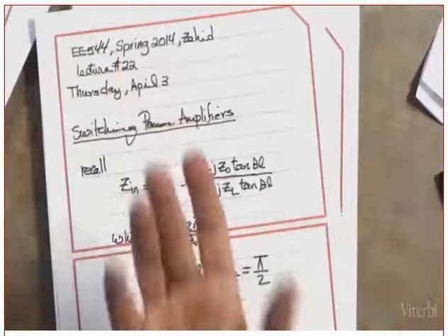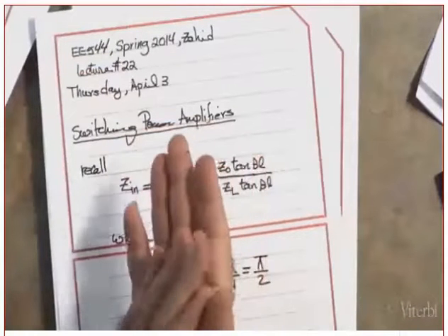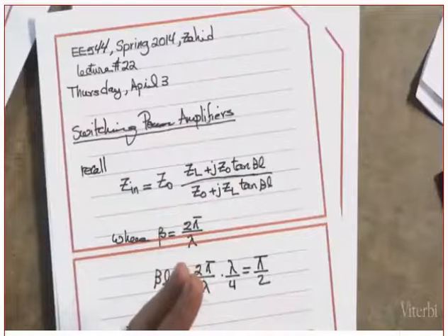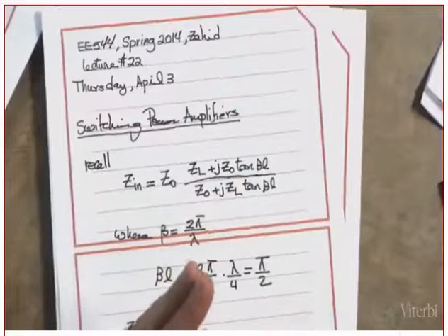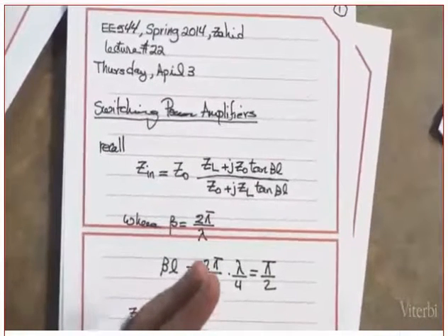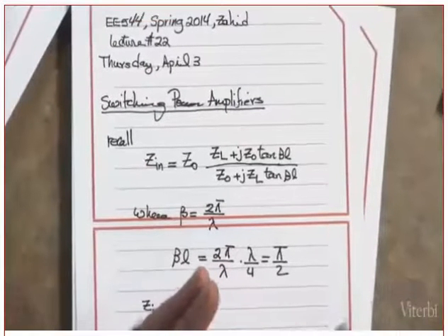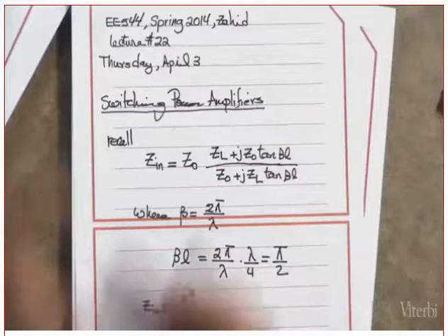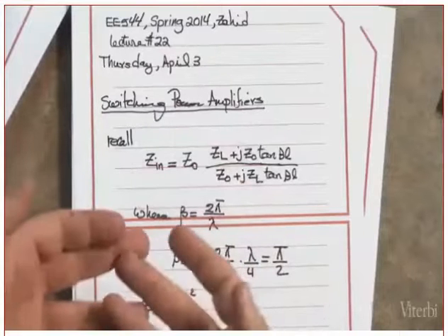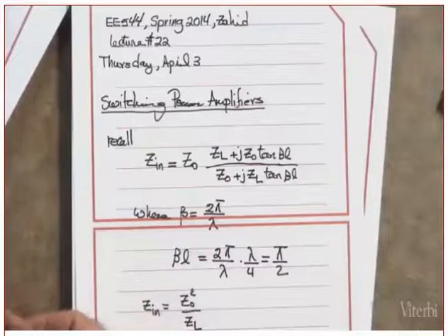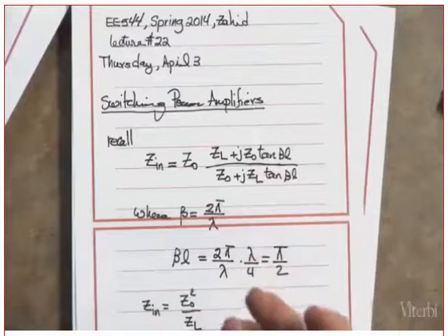Not so good. Are you following? The linearity is not so good. The power mode, the current mode, the constant current mode power amplifier is the other way around. The linearity is pretty good, especially if it is class A, but the efficiency is not so good. The question is, can we improve it? With some techniques, can we improve the linearity, or the efficiency, or both? So in general, the performance.